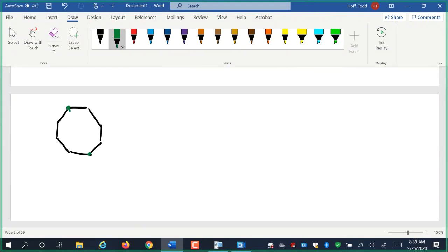If we have a piece of octagonal stock that has a corner to corner length of, let's call it, 1.20 inches, find the area of that for me, please.